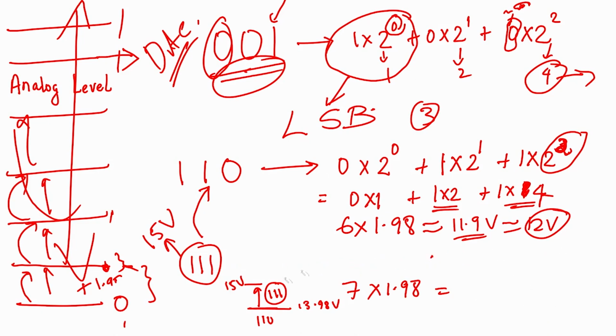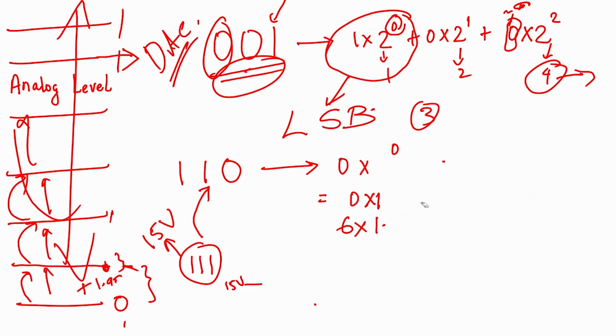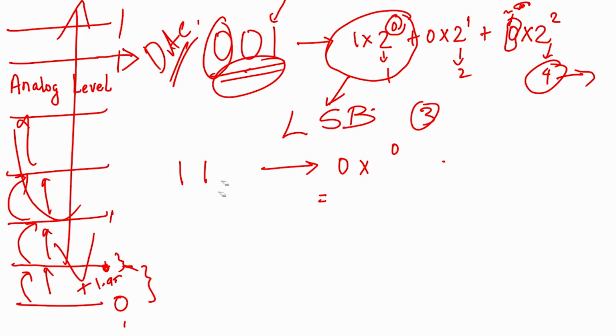This is the whole idea. I have not used any formula as such, we have just gone from intuition to intuition. Just once we accidentally put 3, that's why we got that mistake, but this is 2 raised to 2, and then we were able to get the analog levels very clearly, correct? This is the conceptual basis of digital to analog conversion. There are a lot of circuits to do digital to analog conversion, and there are discrete ICs, correct?